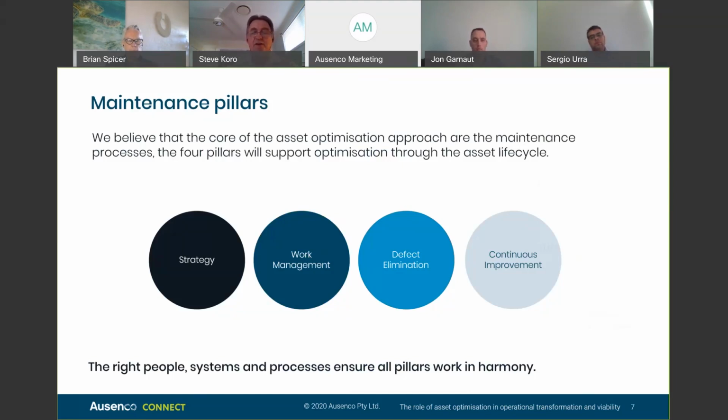Once we've done the work, then we need to do a review and analysis process of maintenance performance and asset performance. And we need to identify from that review and analysis what needs to be improved, and then determine associated corrective actions. So a defect elimination program using RCA methodology helps to improve asset reliability by minimizing unplanned failures, right? Again, basic asset management type philosophy and approach.